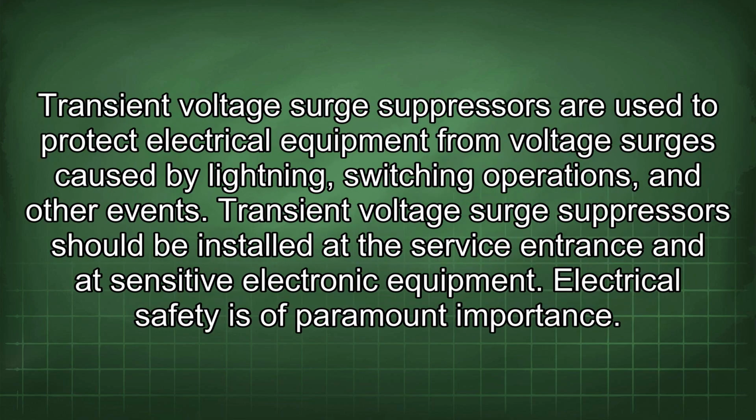Transient voltage surge suppressors are used to protect electrical equipment from voltage surges caused by lightning, switching operations, and other events. Transient voltage surge suppressors should be installed at the service entrance and at sensitive electronic equipment.